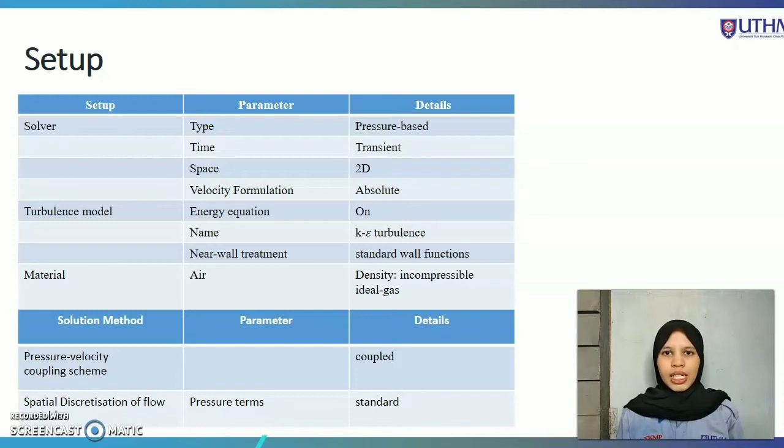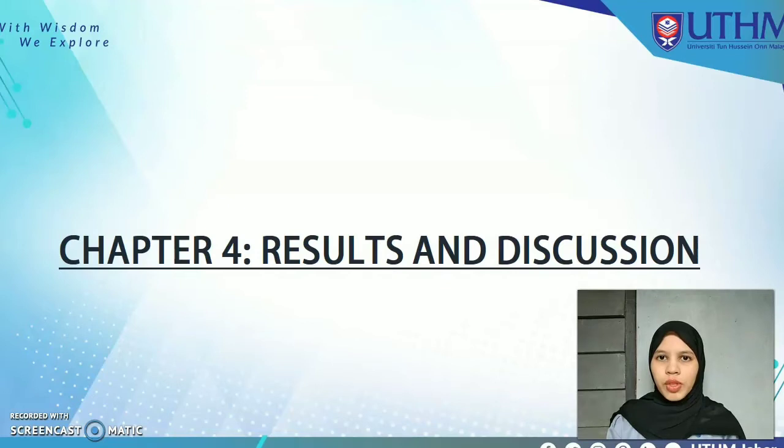Lastly, in setup, it is highlighted that air is an incompressible ideal gas. And also in solution method, the pressure velocity coupling scheme is coupled and the pressure term is standard. After conducting the simulation for piston motion during intake and compression phase, the in-cylinder flow development is studied based on velocity and turbulent kinetic energy.